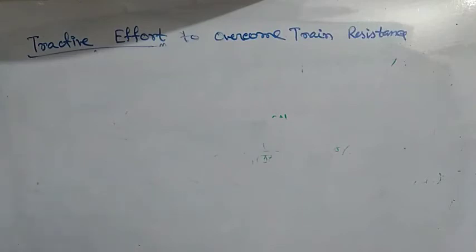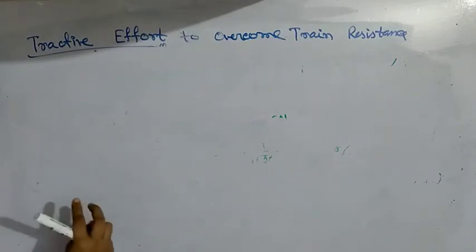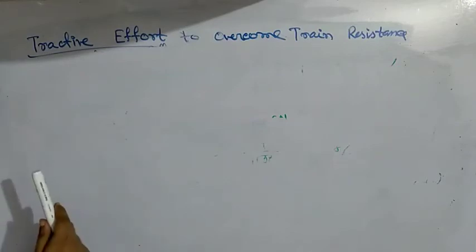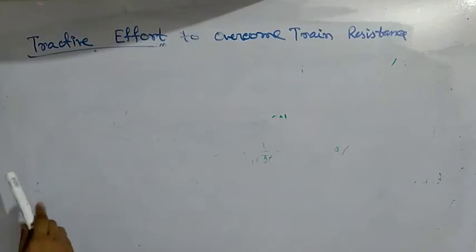Flange friction increases the oscillation of the coach and is affected by the side wind pressure, and track resistance depends upon the strength of the track and nature of the ballast. Aerodynamic drag consists of pressure drag and frictional drag, the former may be due to the ends and the latter due to the length of the train.